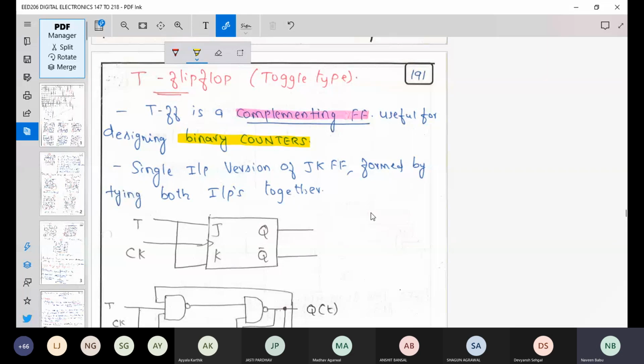So as the student entered, there will be an ultrasonic sensor which will trigger, and then a count will be incremented. Say if your class is at 10 o'clock, after 10:05, if you look at the counter value, that shows the number of students inside the class. Similarly after the class, as students left, the counter will get decremented. So it has to be 0 at the end of the class when all the students have left. Likewise, we designed that counter, but in order to design that counter, we used T flip-flops there. So the application of a T flip-flop is it will count.